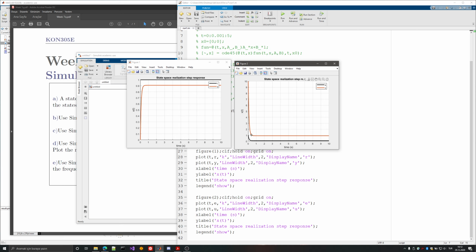But you can see that you're restricted to the shape of the error. So basically, I'm just multiplying this error with a constant, and that's it. I have no transient, no dynamic behavior whatsoever. But if I would have changed the controller structure, if I would have used, let's say, a PI controller or a PD controller, at least I would have had the opportunity to combine the error and its derivative or its integral, so that I have a different behavior. So I don't have that freedom here, because this is the most basic and simplest controller available for me, namely the static gain controller.